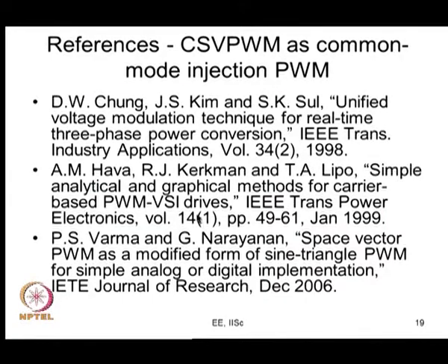I have also discussed this already, but this is just a quick review of that. There are good references. This is a good paper on this, where it talks of the null vector time division and the different PWM methods, continuous and discontinuous PWM methods, you get a discussion on that. You use the 3 phase modulating signals to find out your active vector time, etc. So, this is a good reference.